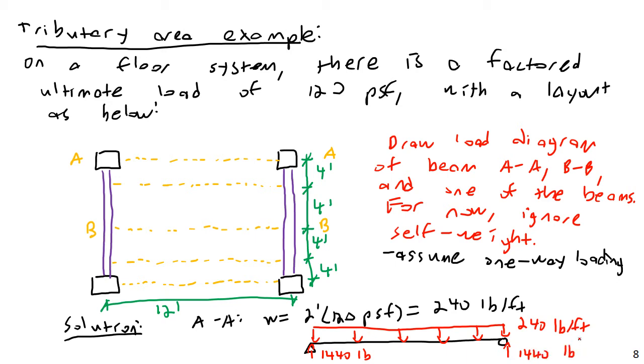All right, questions on that so far? Any questions so far? Yeah. Basically, I'm assuming that it's connected via simply supported. It doesn't have to be. We could have rigid supports, and that would change the bending moment there, and it would also put some end moments. But right now, I'm keeping it simple and just assuming everything's simply supported. But yeah, good question.